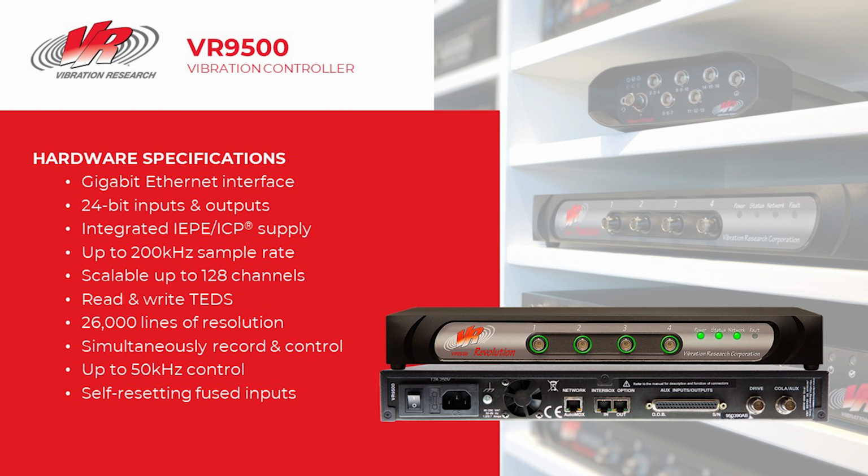The 9500 also understands the Transducer Electronic Data Sheet, or TEDS as it's called, and that's a standard way for sensors to store information about themselves, such as their sensitivities as well as when they were last calibrated. Supporting up to 26,000 lines of resolution, the 9500 can provide outstanding control for high frequency, which is really critical for products with narrow band resonances.